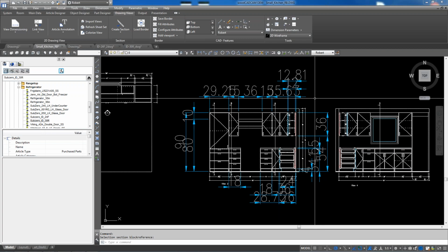And then of course you can go right into the dim style and you can modify your text and font and all that kind of good stuff. And you'll just have to play with it till you get what you really like. Or maybe you've got a dim style that you do like. Personally, I'm not a big fan of this auto dimensioning. There's just not enough controls over what I want to mention and how I want to dimension. And of course, there's nothing that says you can't dimension in AutoCAD like you did also.